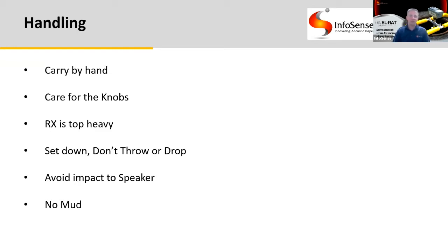Avoid impact to the speaker when carrying the unit, as well as when placing it in the manhole. The speaker magnet can be shifted with enough of a severe impact, rendering the speaker inoperable.